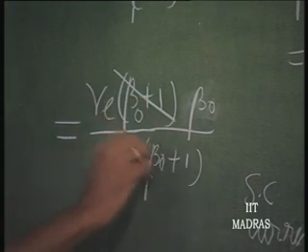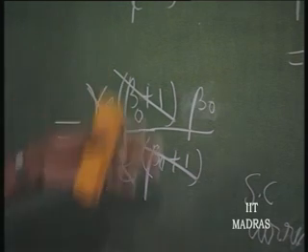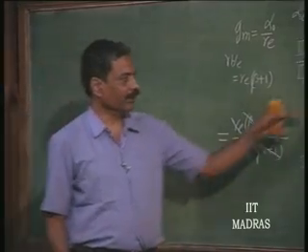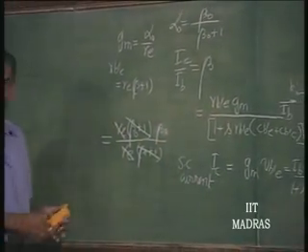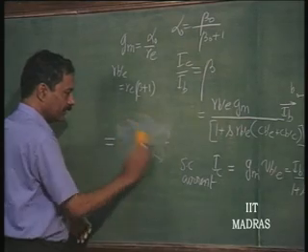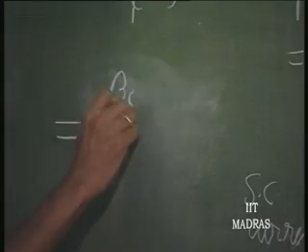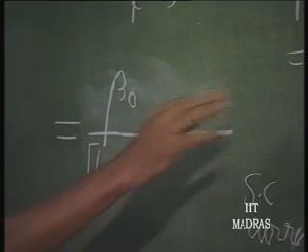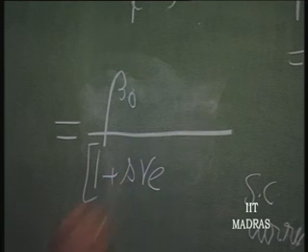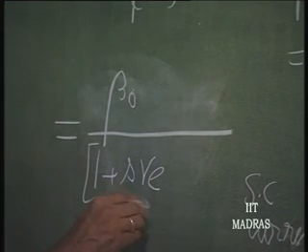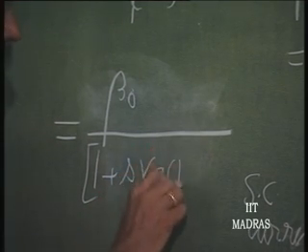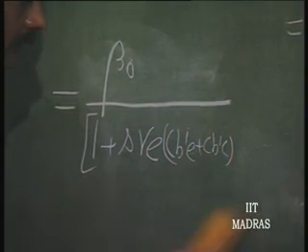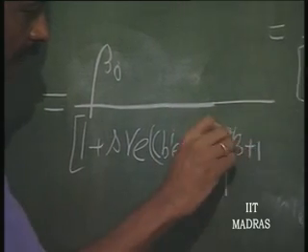So, you can see here, this is low frequency wise nothing but beta naught itself. This whole thing in the numerator is nothing but beta naught. So, we can just say that this is equal to beta naught divided by 1 plus S into, now RB dash E is RE, okay, into beta plus 1. So, we will put that CB dash E plus CB dash C into beta plus 1, beta naught plus 1.